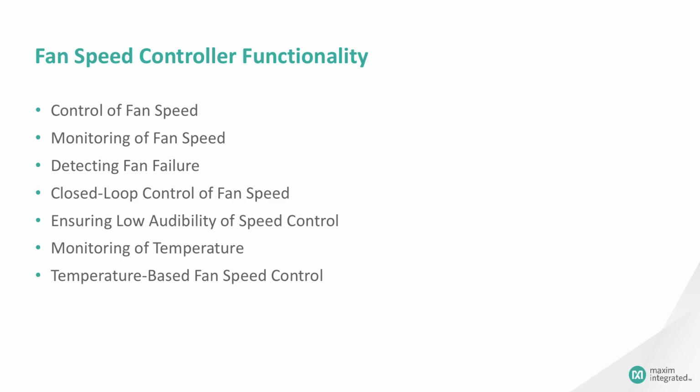Detecting fan failure is usually done as part of the fan speed monitoring process. It can also be done by fans that have fail or locked rotor outputs instead of tach outputs. Monitoring the speed of a fan when driven to its full speed also allows predictive fan failure detection. As fans near end of life, they can begin to slow down. By detecting this phenomenon, a system can ensure that a fan near the end of its useful lifetime is replaced before failing completely.